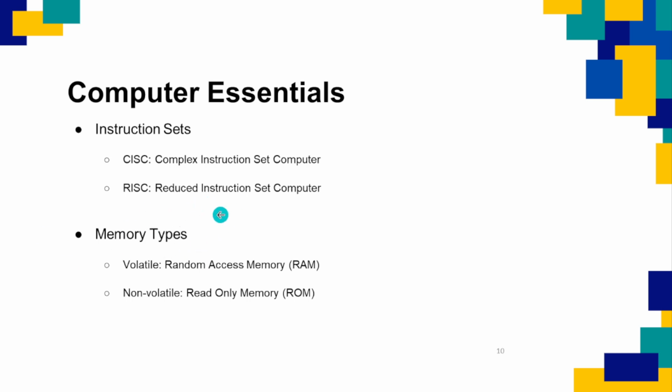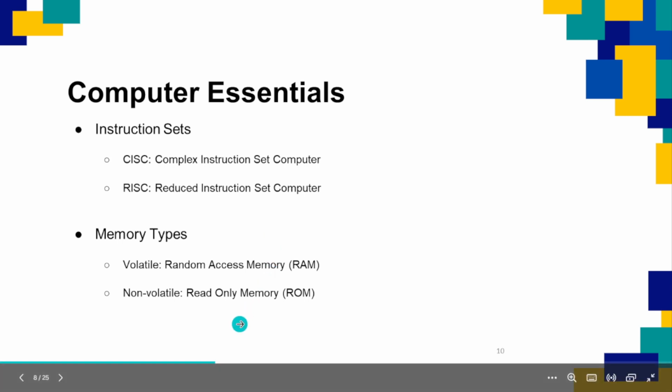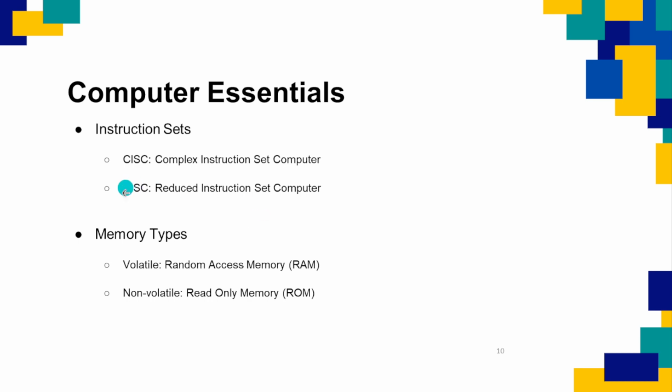These processors have a limited set of instructions, typically with a fixed length, performing only some basic operations. RISC processors tend to favor a simpler and more streamlined design, allowing for faster execution and more efficient use of hardware resources. These instructions typically execute in a single clock cycle, which improves performance but may require more instructions for a complex task. Examples of RISC include ARM, MIPS, and PowerPC.